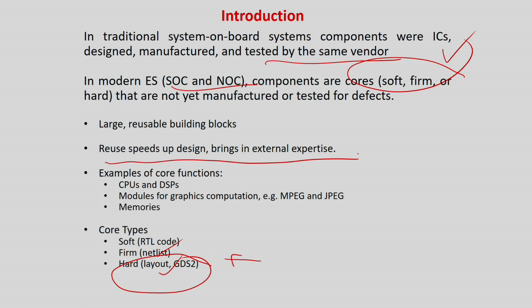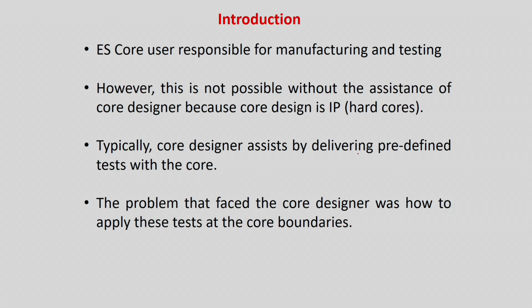Therefore testing in embedded system core based design is a different challenge than what we have been looking at in the first few lectures, that is test pattern generation, how to optimize that and so forth. Here the idea is integration and how to access those internal pins. So basically the embedded system core user is responsible for manufacturing and testing, that is, I am the core user. I am going to fabricate it. You have only given me the design at a soft level, that is at the netlist level or the RTL level, or at the gate level or even at the layout level. But I am going to put everything in a die and I am going to manufacture it.